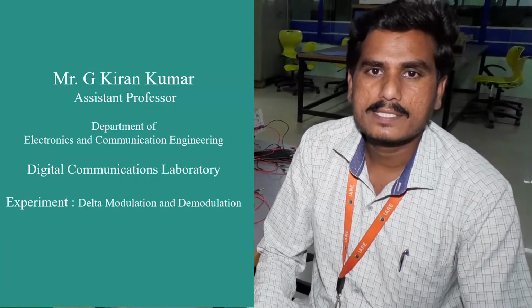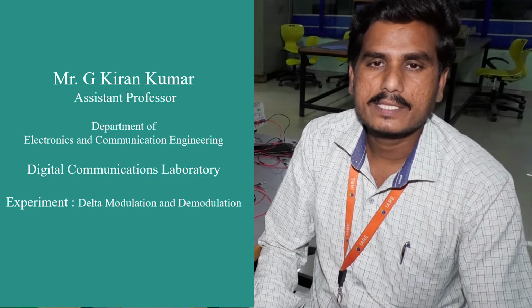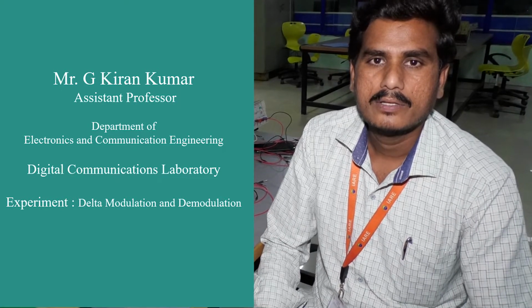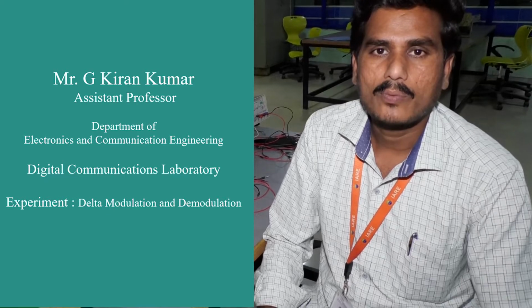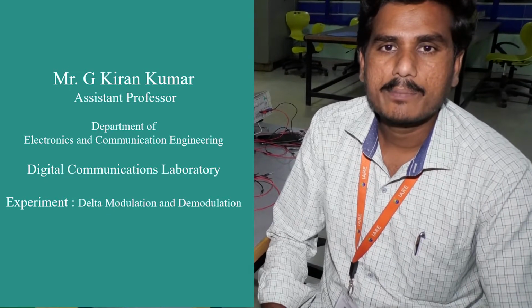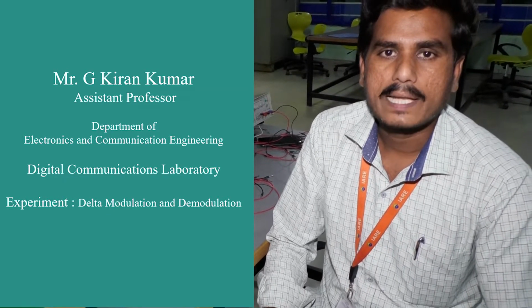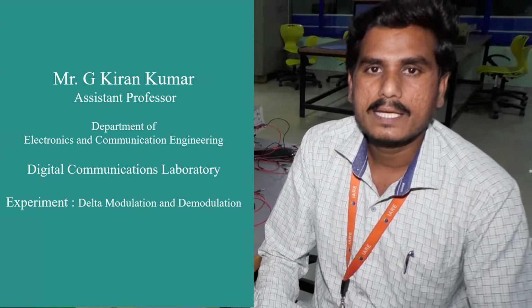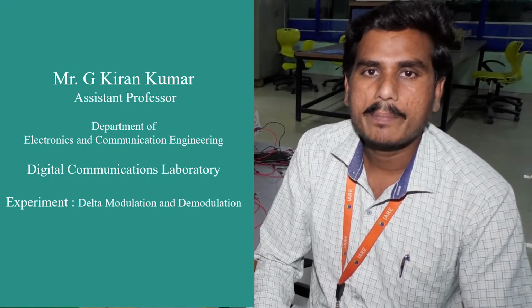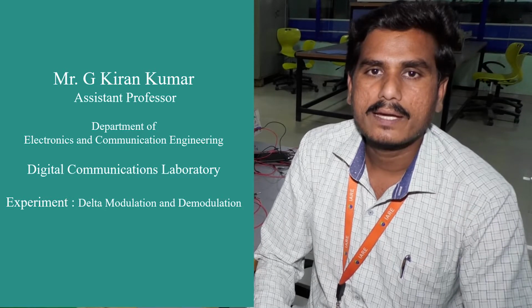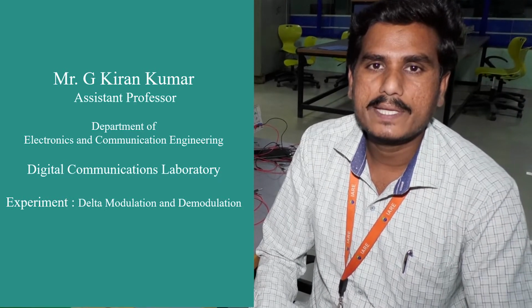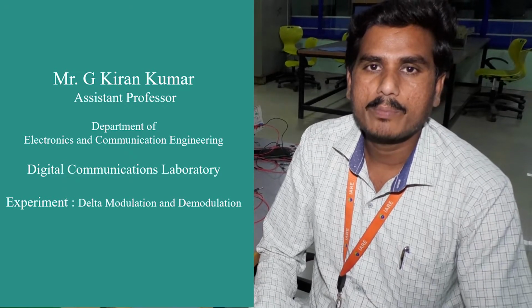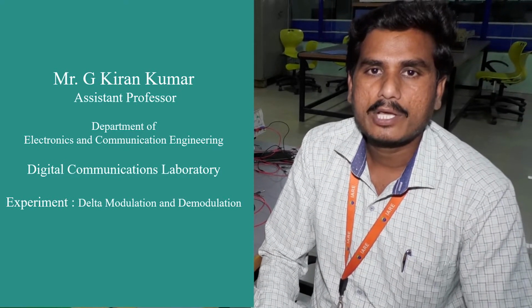Today we are going to discuss the Digital Communication Laboratory. In that we have delta modulation and demodulation. What is the difference between delta modulation and the previous pulse code modulation? Basically, in pulse code modulation, the number of bits per sample is more than 1. Due to that, we have a redundancy problem in PCM. To overcome that problem, we go for delta modulation.